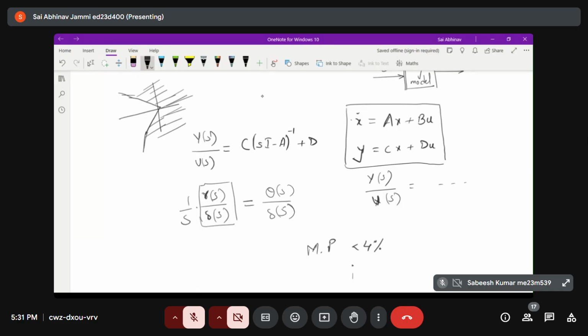exercise, before going to the RL tool directly, we'll construct the Routh array. The Routh array will give us the possible ranges of Kp and Ki if there is a PI controller, so that the system stability is maintained. As you know, system stability is of prior importance to the performance.